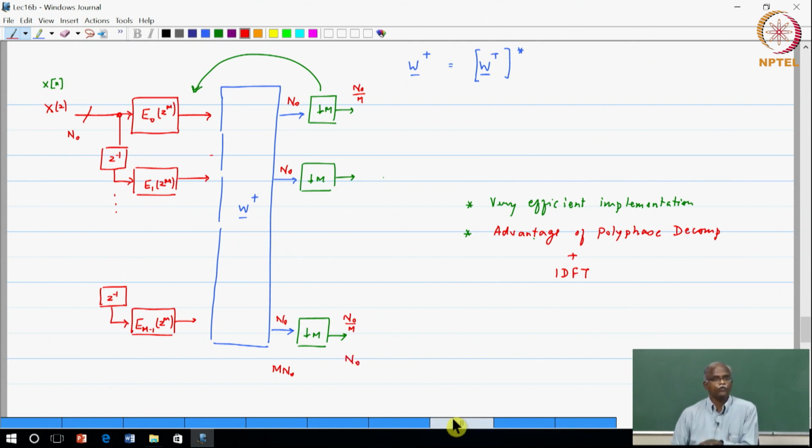So, this is more for storage or for efficient processing. Again, you need not do it, but if you do it, you get the maximum advantage of the polyphase structure. One of the reasons we would do it is that you can downsample by a factor of m, retaining the input and output sample rate at the same level without loss of information.